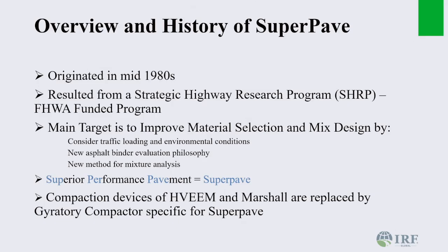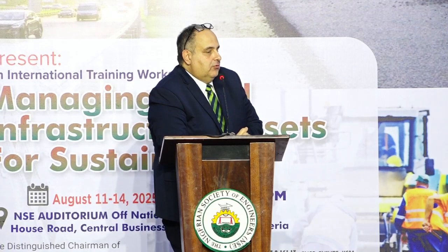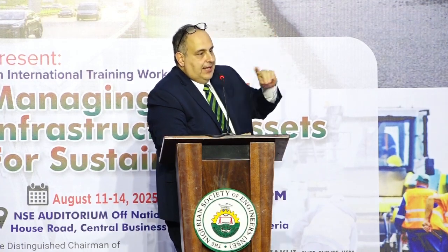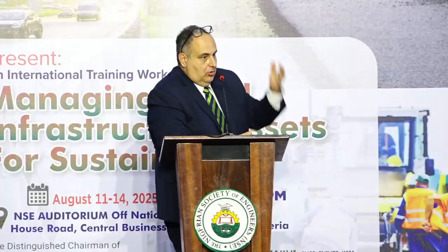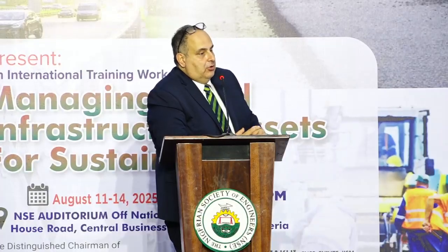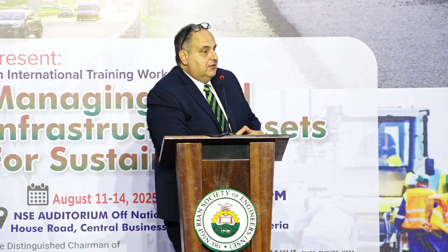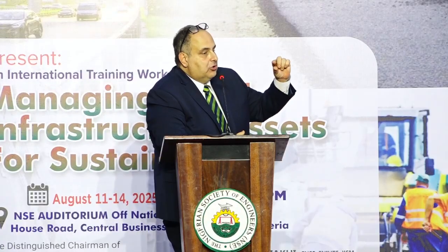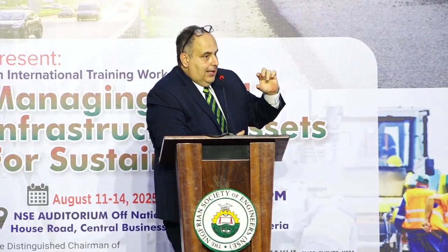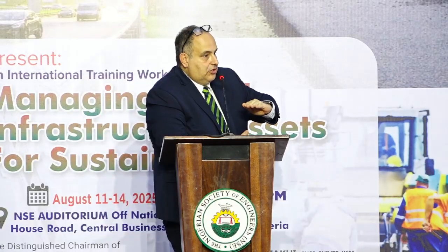No. Remember, this is a volumetric mixed design. So, meaning volumetric is you try to find the components that add up to 1 unit volume, right? Whether the unit volume is cubic meter or cubic yard. The unit volume of the ingredients. Now, the ingredients in asphalt, the major difference compared to any other ingredients, whether we talk about soils or concrete, is the intermingling between the binder and your aggregates.